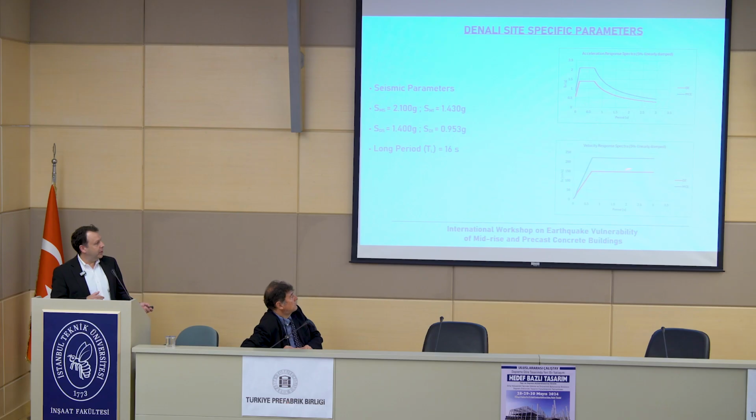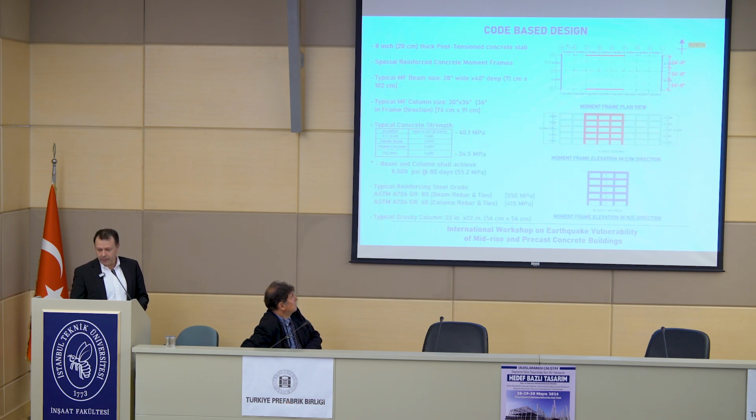So we have both the maximum considered earthquake, that's the one in blue, and the design basis earthquake, which is the one in red. On top there is the spectral response spectra, and on the bottom we've been making sure that we look at this because it makes it really clear that slight shifts in period really don't impact your spectral velocity. So you can consider that as always a basis of design, because small adjustments in that period do not have a big impact on your spectral velocity.